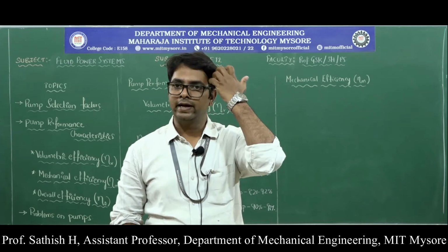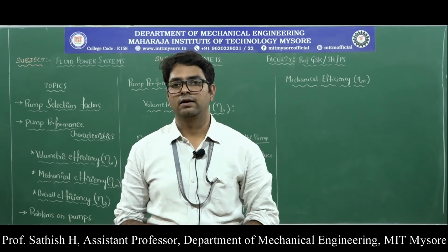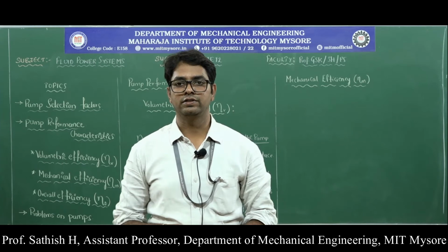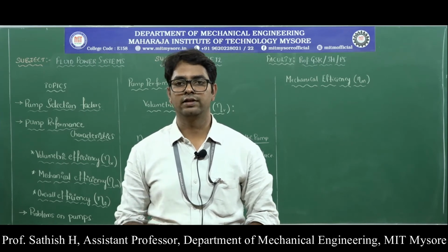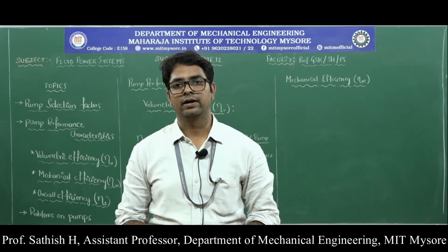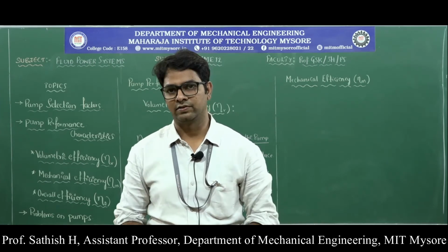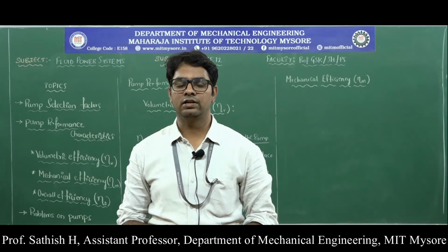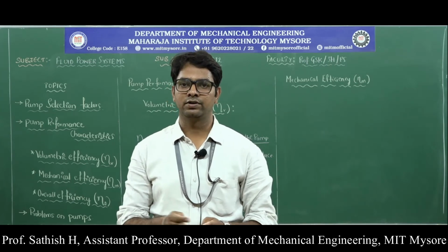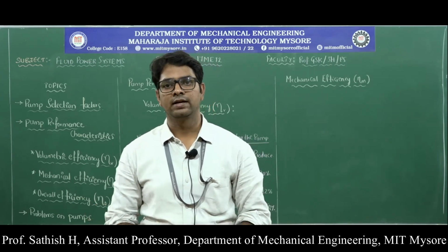Also, mechanical efficiency losses come from the turbulence of the fluid inside the pump. So that also contributes to the mechanical efficiency. These are the energy losses that are accommodated in the mechanical efficiency. The mechanical efficiency is normally between 90% to 95%.